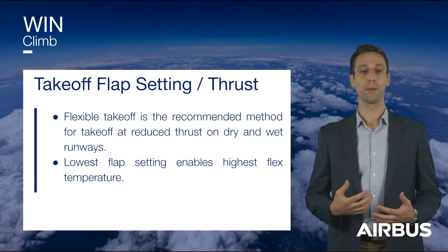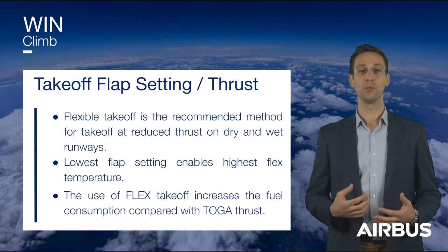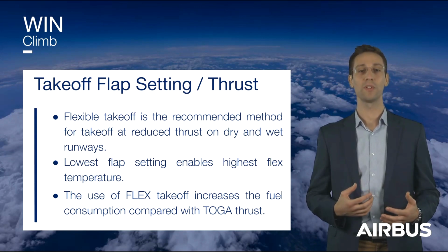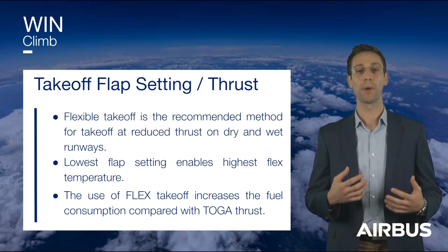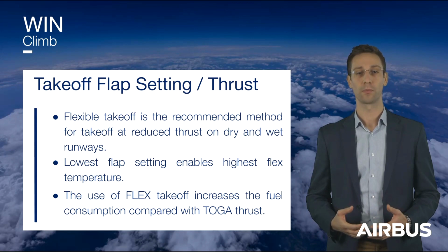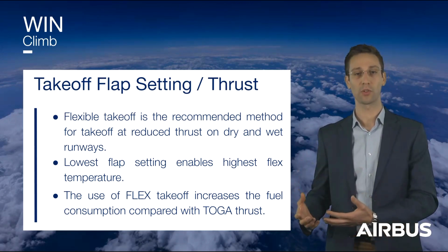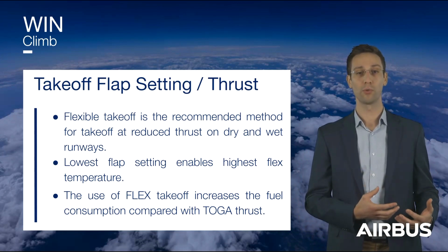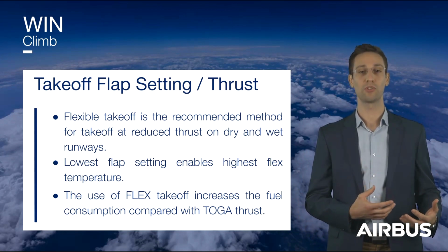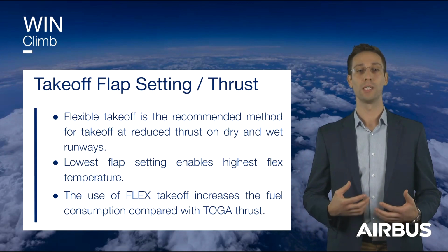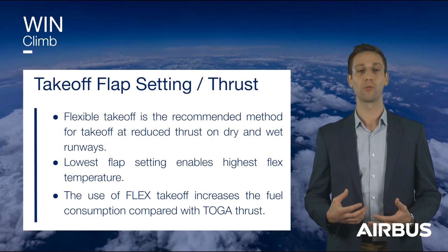It is also important to have in mind that the use of flex takeoff increases the fuel consumption compared with the TOGA thrust. Once again, a right compromise between maintenance costs and reduction of fuel consumption and CO2 emissions needs to be found depending on your operational constraints.